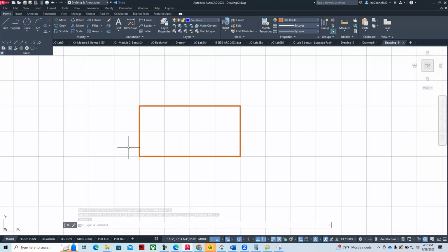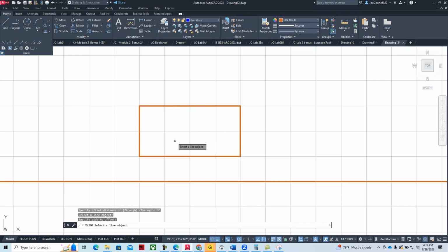And then we're going to go to the X line, and we're going to offset this line 3 feet. So we'll say X line, and then we're going to go down and say offset, and this was down arrow on the keyboard while you're running with dynamic input, offset, 3 apostrophe, select the line, and then the side.